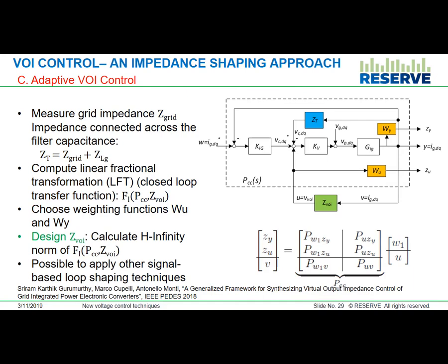Now you can see that the design objective is this: this entire control transfer function of the inverter is like the plant that we want to control, and the objective is to synthesize this ZVOI such that the output current has a certain characteristic.